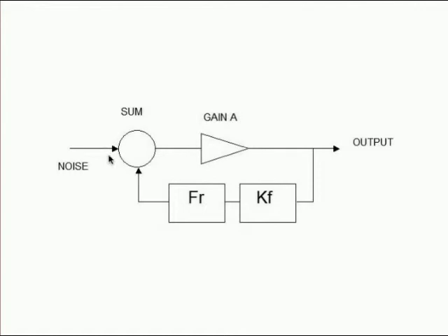In the absence of feedback, a very small noise input here would be amplified by the gain of this amplifier, and you still have a fairly small noise at the output. Possibly we might have 10 dBs gain or something like that. But when we've got this positive feedback system, which is actually providing a massive gain, we have a tiny noise input signal, which is much smaller than the feedback, and it ends up as a big output signal.